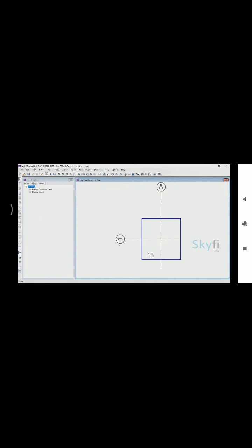Now that the design check is done, and you have fixed the footing dimensions, you will now generate the detailing diagrams of the reinforcement. Go to Run, and click on Run Detailing. Mark all the 3 options, and click on OK. The different detailing diagrams have been generated, which you can view one by one. Go to the Detailing tab of the Model Explorer. Expand the Drawing Component Views option. Again, expand the Footings Views option.